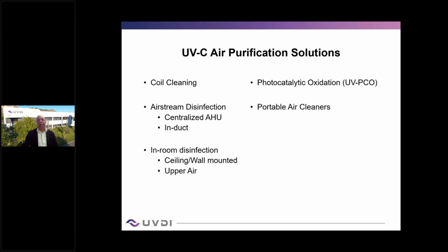Photocatalytic oxidation is activated by UV. That's why it's on the list, and it has been shown to be very effective in reducing gases, contaminants, VOCs, and odors. And there's a whole line of portable air cleaners which uses UV in addition to all the other technologies. And there are air cleaners which use UV for disinfection and photocatalytic oxidation as well.